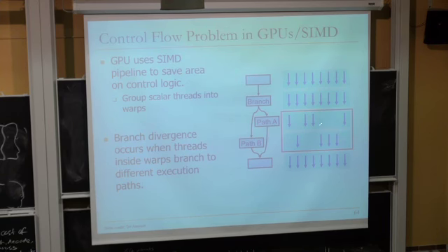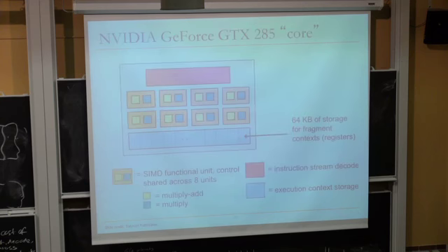Let's say you had other warps, 1, 2, 3, 4, 5, 6, 7, 8, that are also doing the same thing. You may be able to figure out which ones are actually executing path A and which ones are actually executing path B, and pack different threads together. So some GPUs actually do this optimization in hardware to improve the efficiency of this. I'll let you think about that.